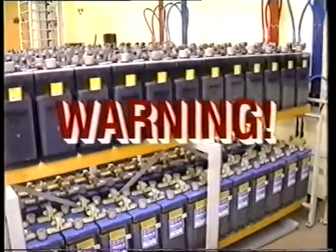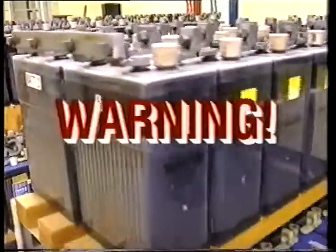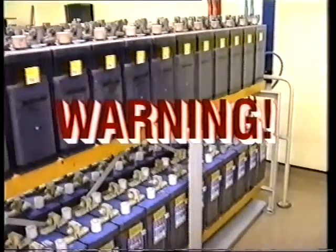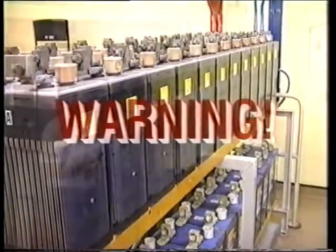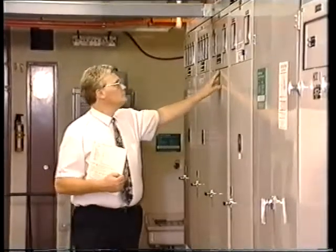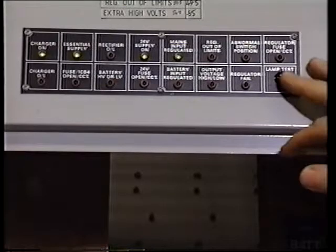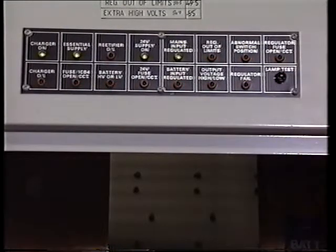However, any period of AC isolation to more than one unit must be well within the standby battery reserve time, otherwise long-term battery operation will lead to total failure of the exchange load. Step 1. Check that all buck-boost power supplies are online, supplying current with only the 4 green indicators on. Now check that all the indicator lamps are functional by operating the lamp test push button before proceeding.